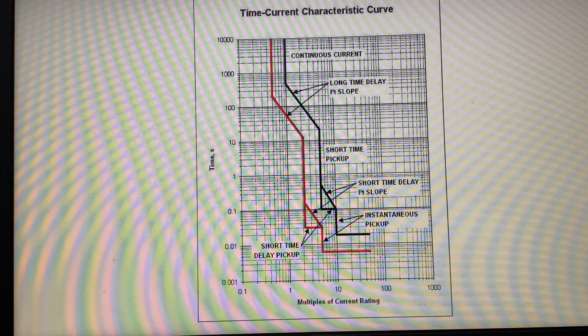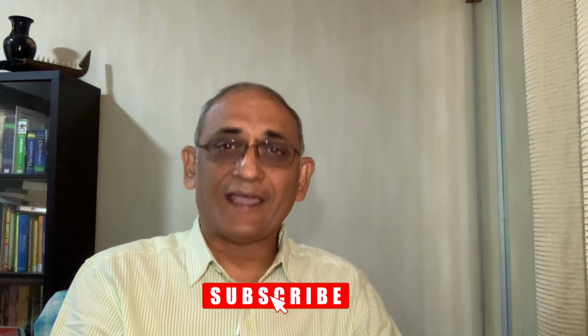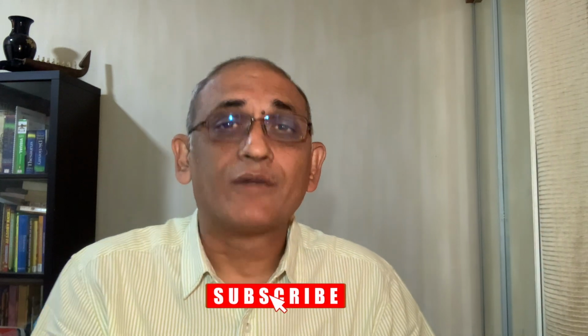Anyway, let us leave that to the specialist. Just know that it cannot be an arbitrary setting, it has to be studied and the breakers have to be adjusted as per the time current characteristic curve. So, I hope you have understood how breaker coordination can help in increasing the overall uptime of the facility and also faster identification and rectification of faults, and also avoid nuisance tripping by limiting the power outage to a branch of the network where the problem occurs without impacting the rest of the network.